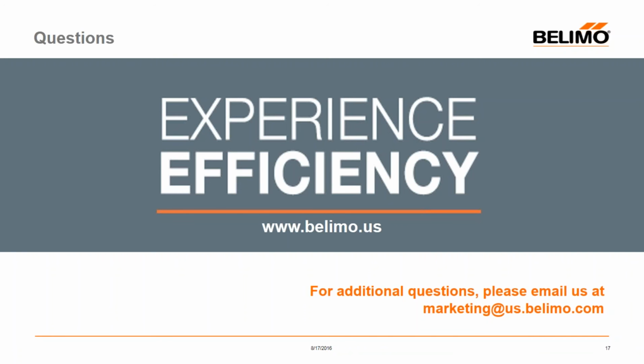Where are these energy valves most used? In which situations do you see the most cost savings? That's a hard question to answer on the surface. Pretty much in any air handler unit or heat exchanger where you are experiencing low delta T syndrome, that's where you would want to use them. There are two basic operations. One is to control delta T and increase coil efficiency. The other is data acquisition and the ability to document exactly what the valve is doing. So you'd have to look into those two scenarios.